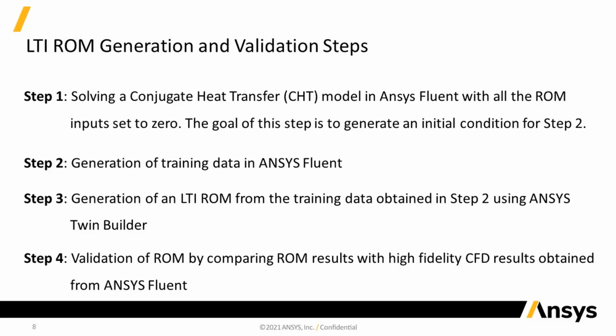In the second step, we generate training data in Ansys Fluent. In the third step, we generate an LTI ROM from the training data that we obtained in step 2 using Ansys Twin Builder. And finally, in the fourth step, we validate the ROM results by comparing them with the high-fidelity CFD results obtained from Ansys Fluent.